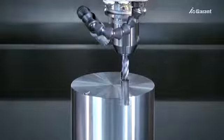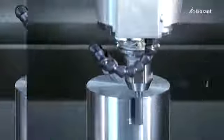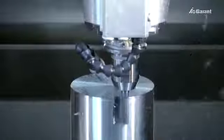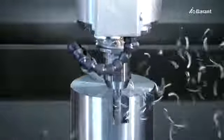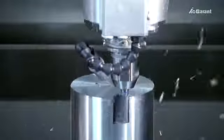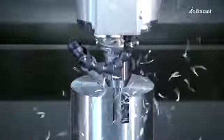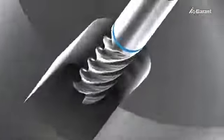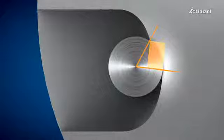It's entirely different for TPC milling. Here, the value which formerly was constant is continually recalculated by the CAM software or the machine controller. This results in a completely new pattern of movement for the tool. Let's look at this in more detail. Ae, the contact width, is now continually recalculated. What was constant is now a variable.